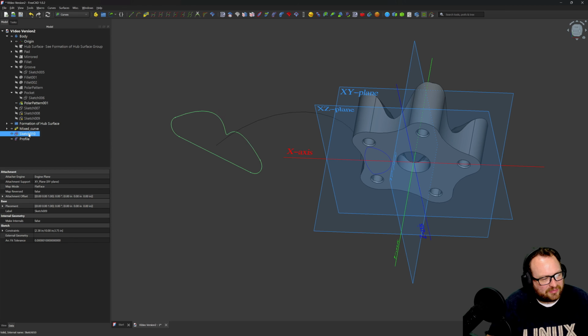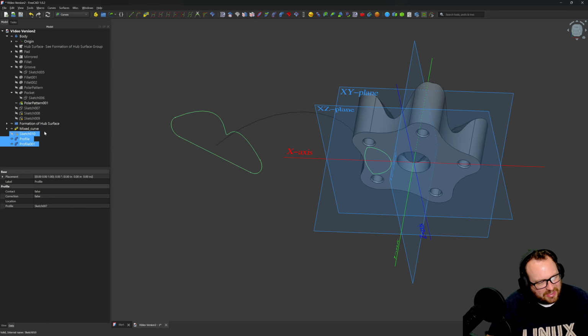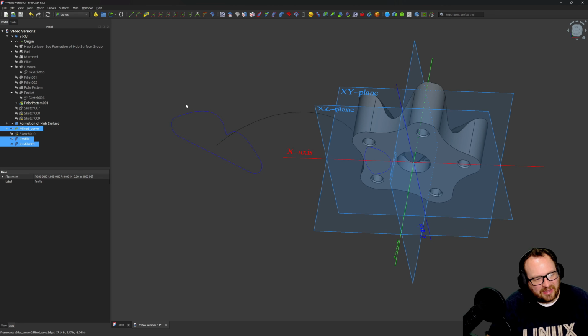Again, with sketch 10, we'll click this button, pipe shell profile, and it again becomes what you would think of as a fit spline. Now we'll do a pipe shell profile, and here's a little thing to keep in mind. I select my 2 profiles from the tree, I go select my mixed curve, and everything looks good. I click on pipe shell, and nothing happens, right?